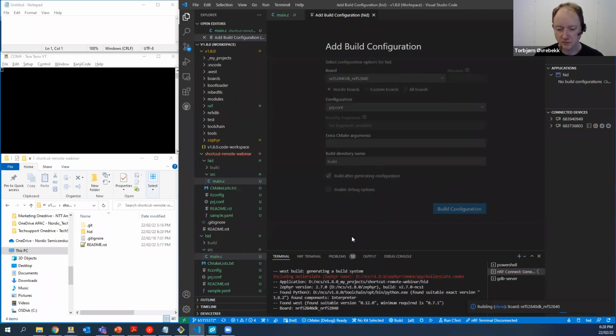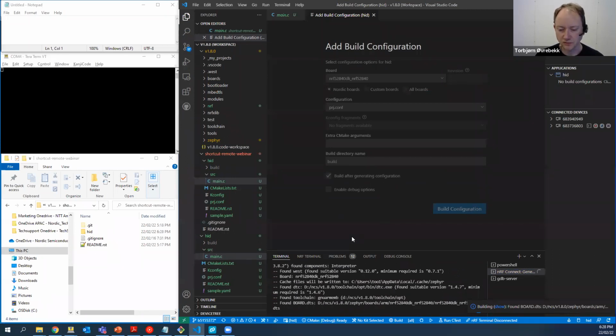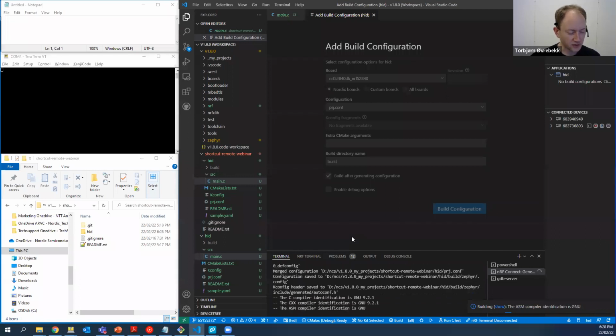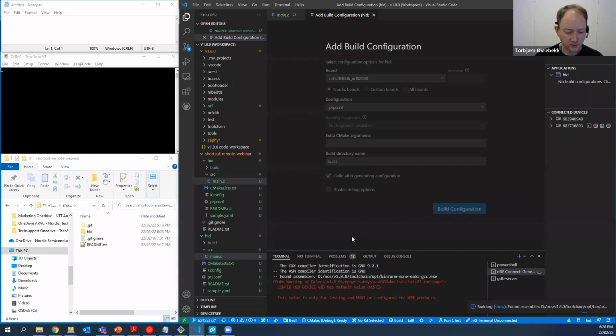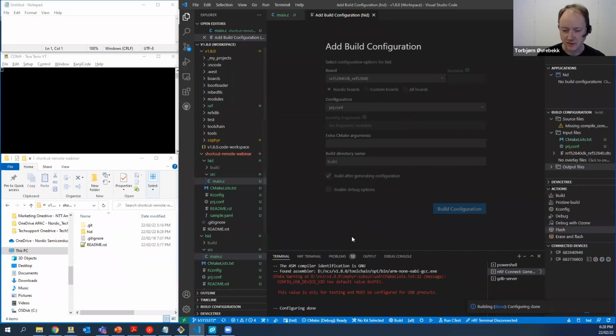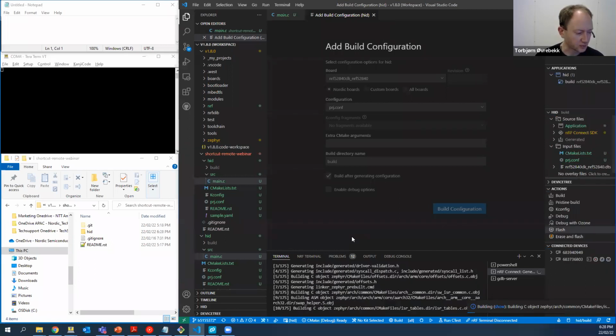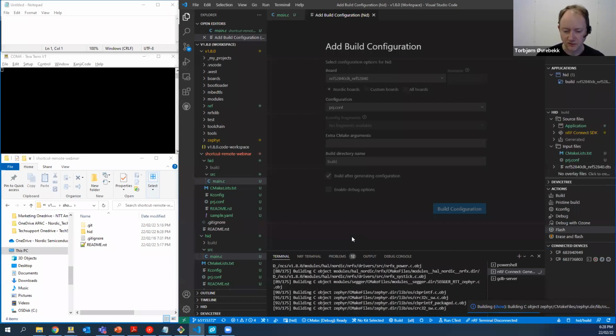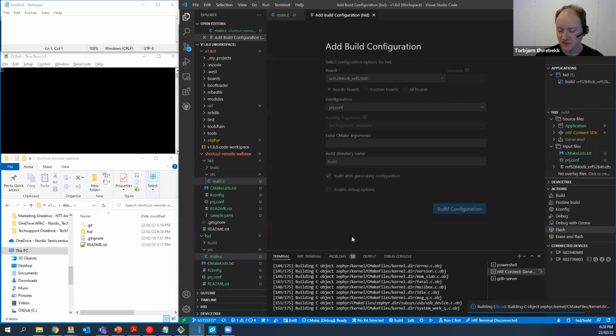When you do build, it's going to run through a full project configuration and build phase, which can be a bit slow. One tip if you're running on Windows is to disable automatic virus detection on the folder where you store NCS. I just tested this today and found it to speed up the build process quite a lot. On Linux and Mac, this is typically faster, at least if you compare it to a Windows installation with this virus detection installed.